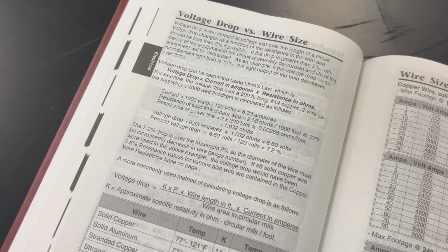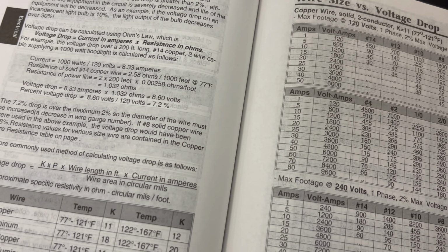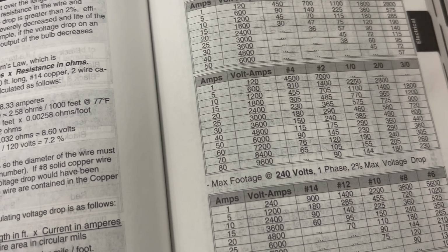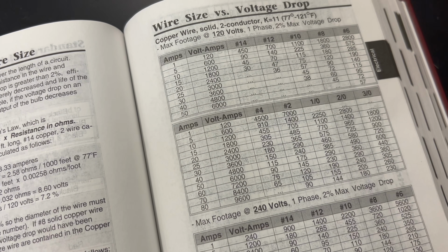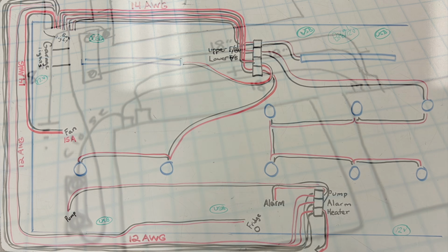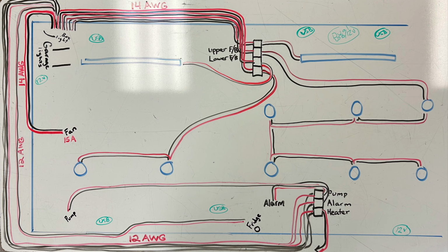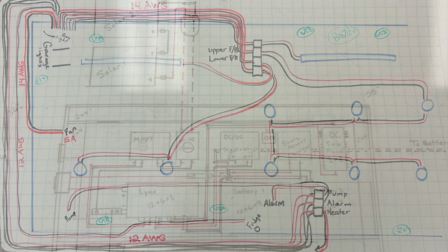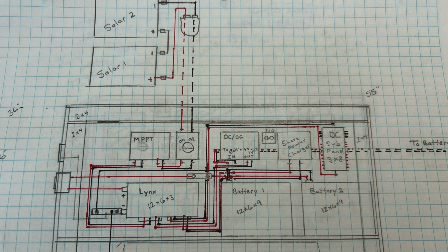If you want to take a deeper dive into wire sizing, you also need to consider the length of the run and how it relates to voltage drop and resistance. In general, keep your wire lengths as short as possible and plan your layout to reduce unnecessarily lengthy runs. This can affect where you place batteries relative to voltage-sensitive devices like your solar panels, chargers, and inverters.